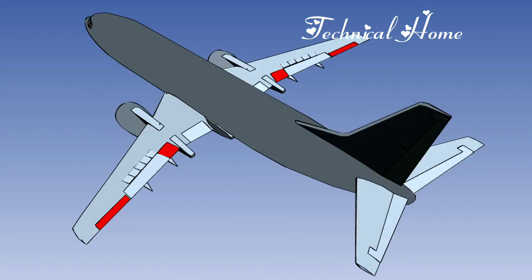The trailing edge flaps, which are discussed in another lesson, and the ailerons, both occupy part of the trailing edge of the wing. For good takeoff and landing performance, the flaps need to be as large as possible. And for a good rate of roll, the ailerons need to be as large as possible. However, space available on the wing trailing edge is limited, and one solution is to droop the ailerons symmetrically to augment the flap area.